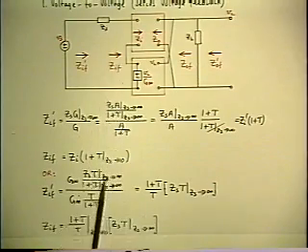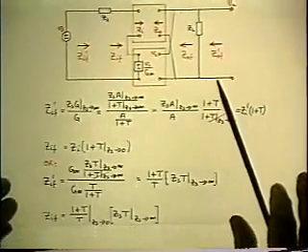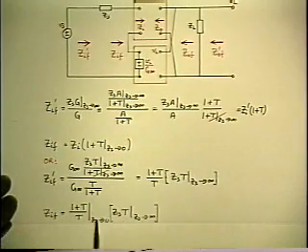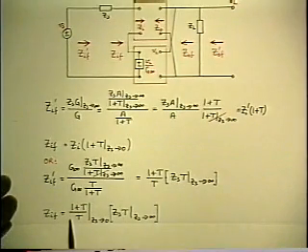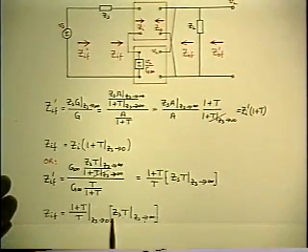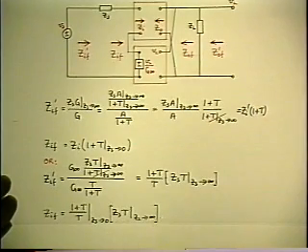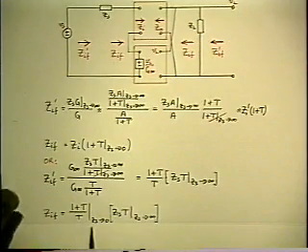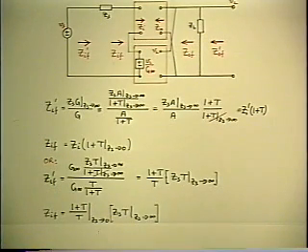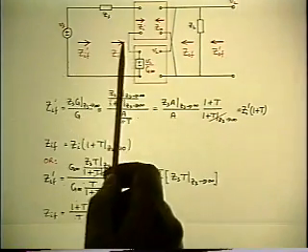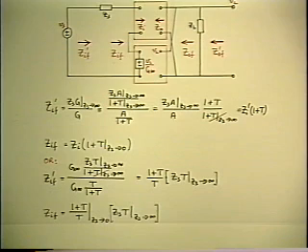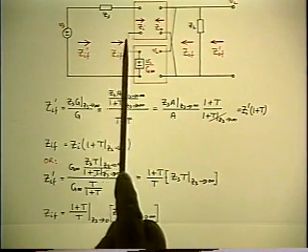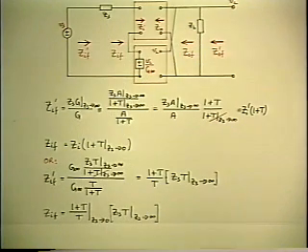And if you want the inside input impedance with feedback, take the other limit in the result, which means let ZS go to 0 in the first factor. It's already limited out of the square bracket, so that doesn't change. The only difference between the two is the factor in front, both of which are almost 1. So the inside and outside input impedances are almost equal with feedback. Therefore, both of them must be much bigger than ZS.